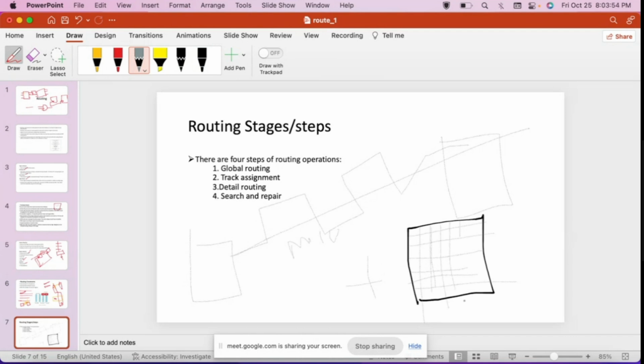When you turn on the M1 metal layer, the grid will show. You can switch on and switch off your metals; there is a control panel here when you look into the tool. When you switch on M1, the grid looks like this, so you have to route metal in this way, exactly following it. Each layer has some color. Metal 2 has to be routed over the line like this. But when you go for the higher layers, instead of grid, you can go for half grid also.